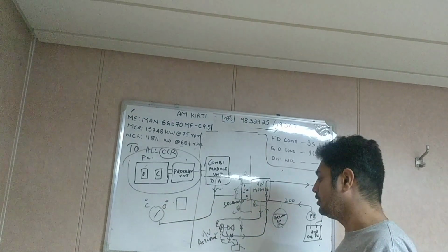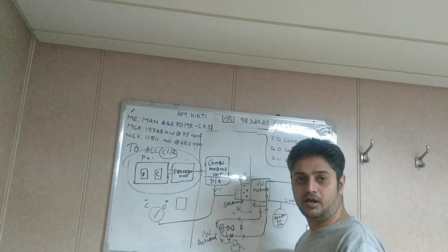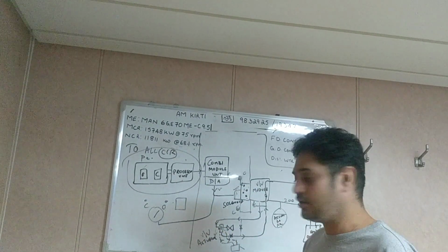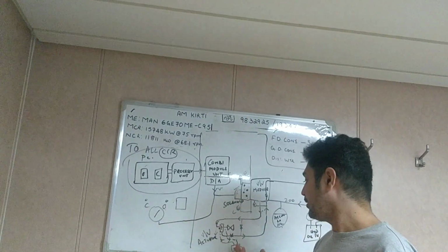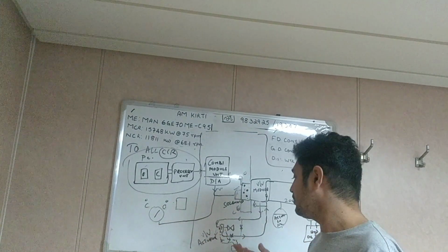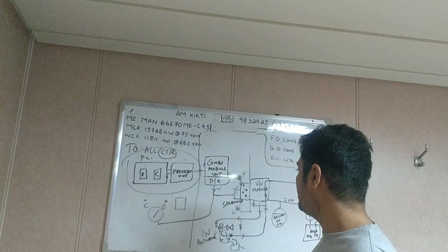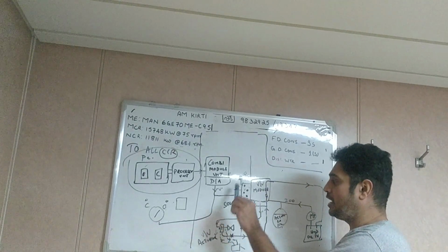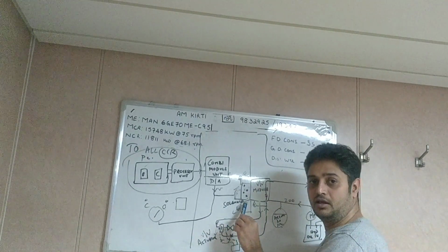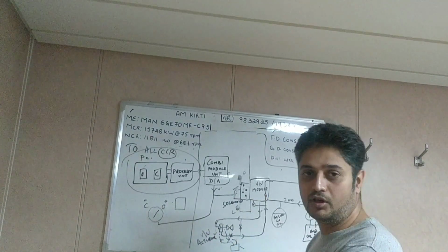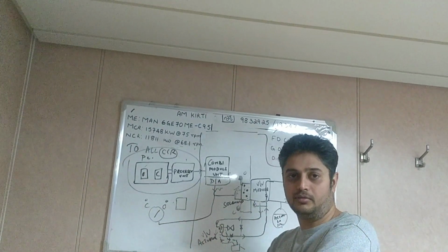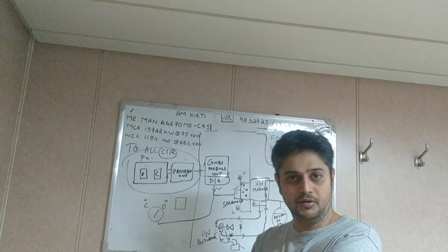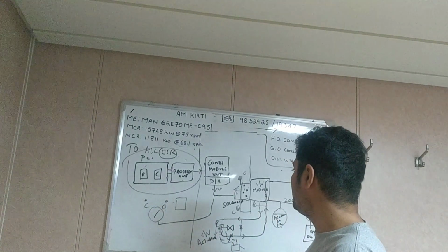So what will happen is, suppose you are able to open it manually, either by pump or by hand. Bigger valves you cannot open by hand, you have to use the hand pump. If using the local emergency hydraulic pump it is opening freely, and the solenoid is also getting energized and manual operation is also happening, then you see whether you can change this valve module. One by one you have to see how to troubleshoot depending on your system. Usually the problem will be in the valve module.